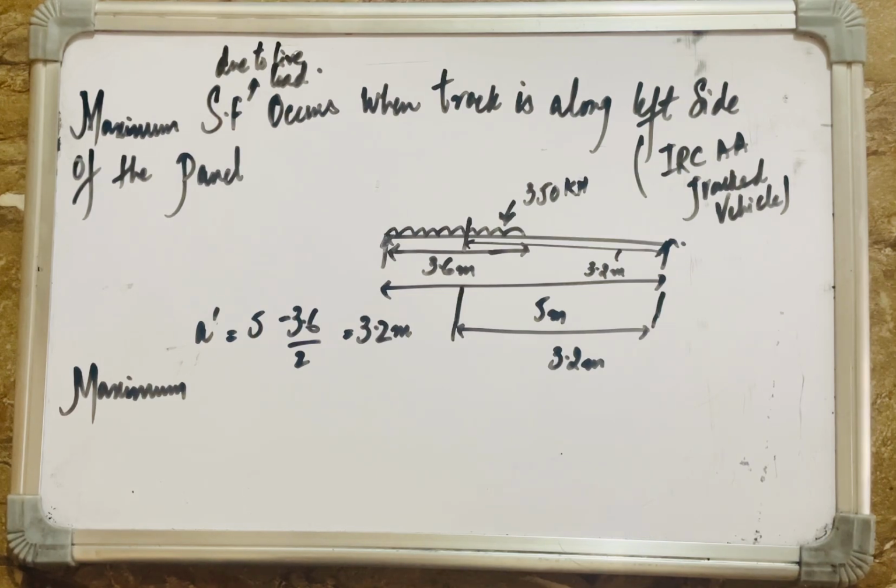We did the same in the case of deck slabs. We calculated the moments and then accordingly we saw what type of reinforcement we are going with. In the same manner, during the design of stringer beams, we have to first calculate the moments. Moment is the ultimate criterion on which our design process is based, because we have to calculate what moments are going to be generated there. Then only we can design the sections. So in case of cross girders, stringers or deck slab, the first and foremost step is to calculate the moments.